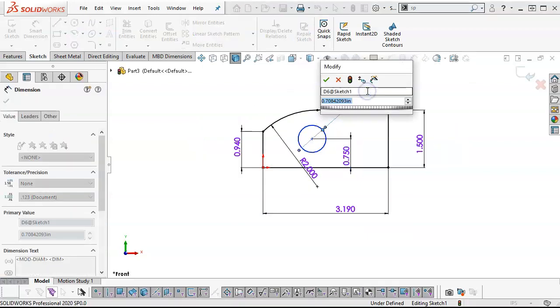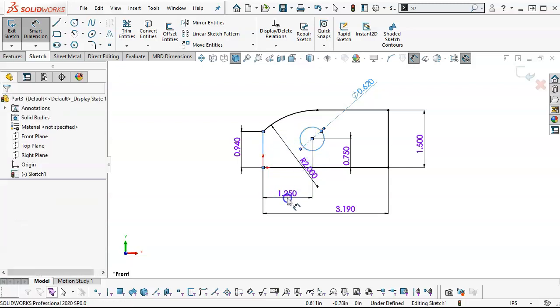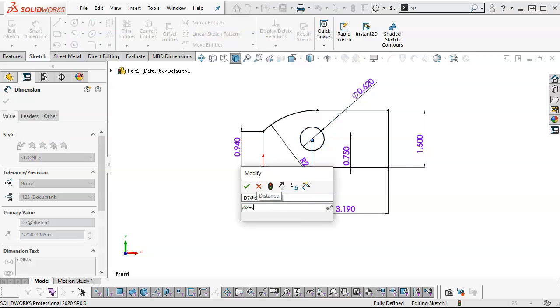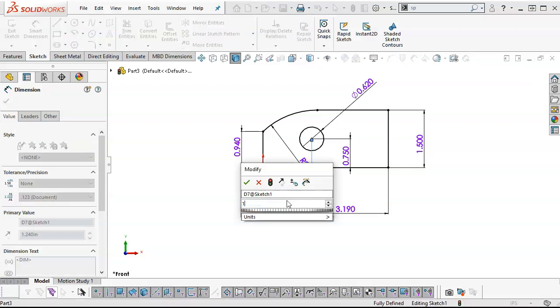to complete that test. Alright, so we have a limit dimension 0.62 to 0.63. Maximum material condition will be 0.62. And those are set up to be in line. And our width was 0.62 plus 0.62, which would be 1.24. So let's do that math, 0.62 plus 0.62.